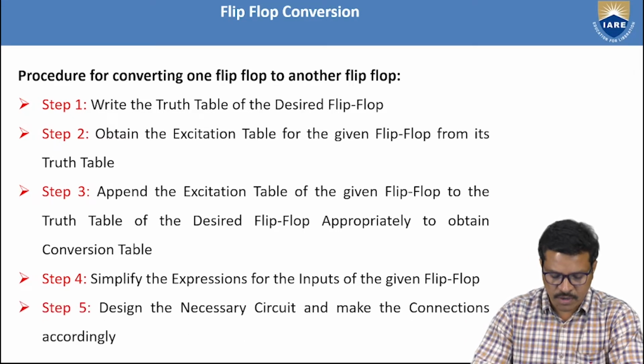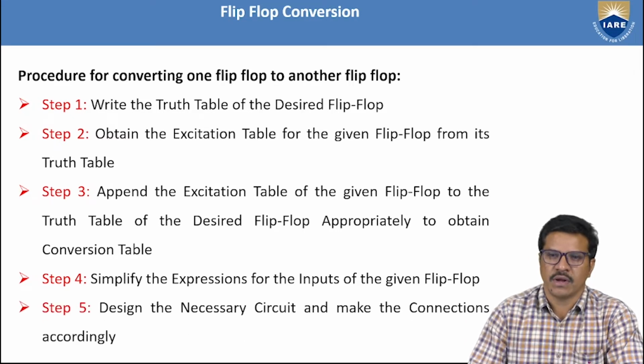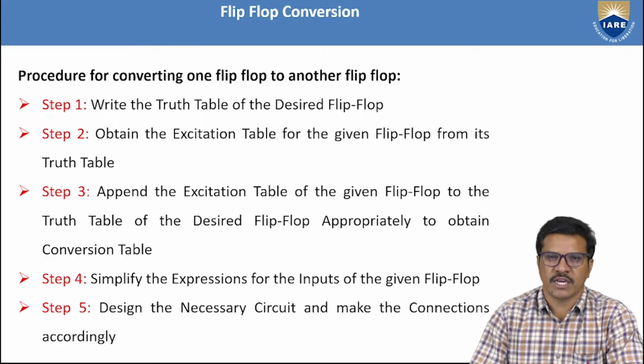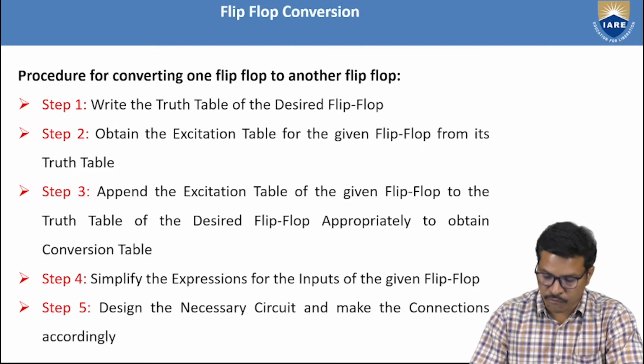In the fifth step, design the necessary circuit and make the connections accordingly. So by following these 5 steps, we achieve the conversion from one flip-flop to another flip-flop.